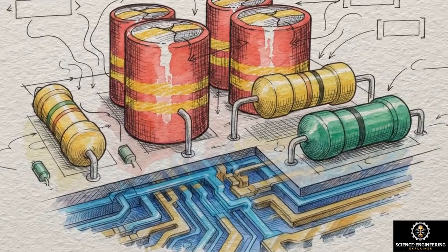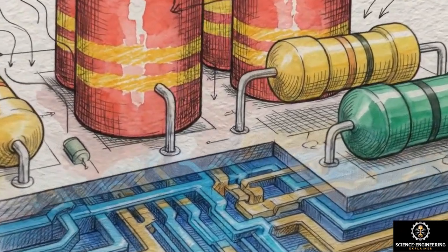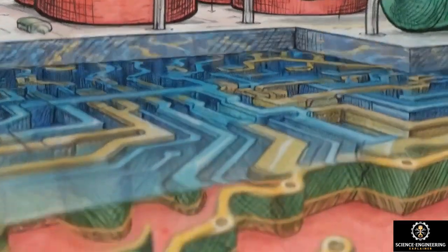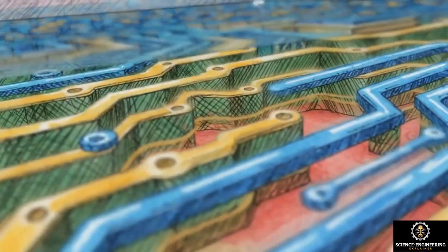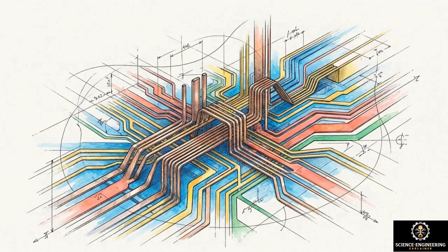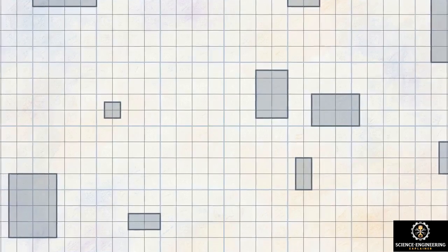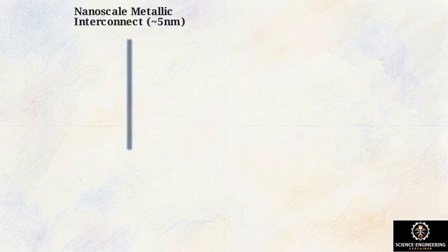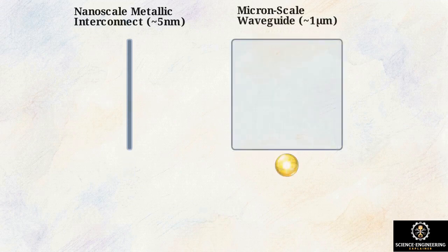Optoelectronic Integrated Circuits, or OEICs, resolve data bottlenecks by merging optical communications and silicon logic on a single semiconductor substrate. Modern electronic microprocessors achieve high density because they rely on metal interconnects. These metallic traces scale down to sub-10 nanometer dimensions, allowing engineers to pack billions of logic gates into a confined physical space. But optical components require dielectric waveguides to carry photons.